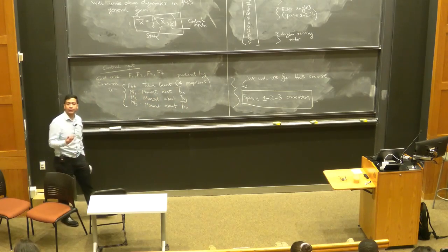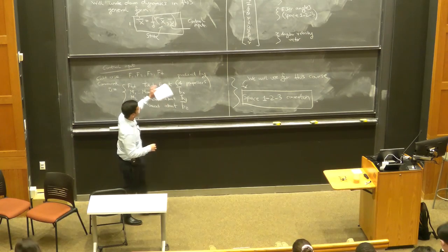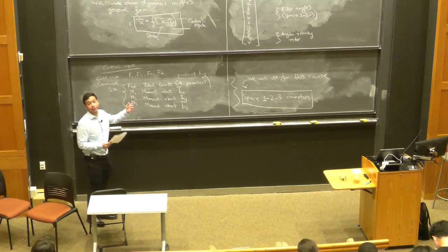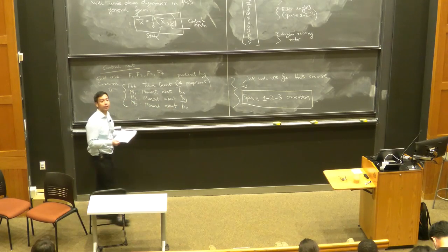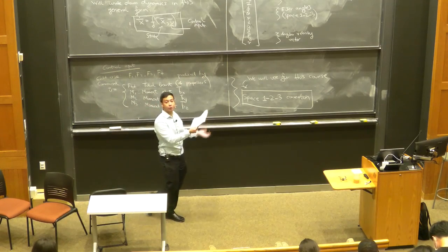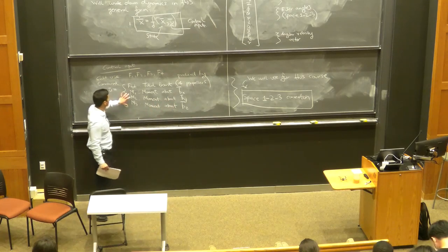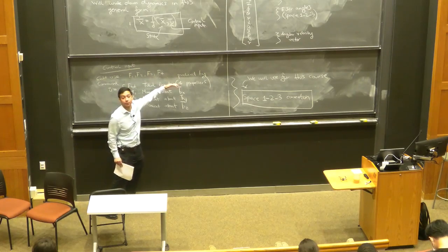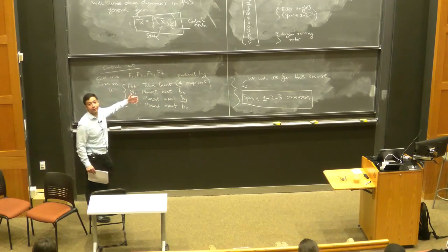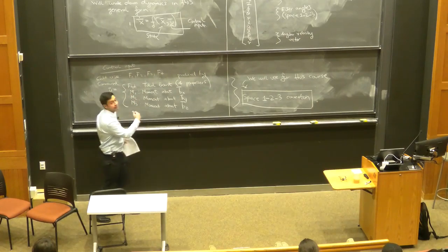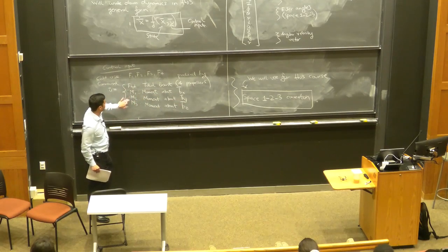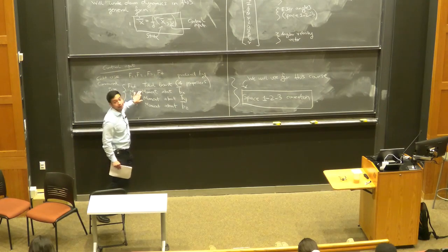This is similar to what we did with the planar quadrotor, right? If you look back at the equations of motion we wrote down for the planar quadrotor, we wrote them in terms of two control inputs, U1 and U2. U1 we defined to be the total thrust, U2 the total moment. So this is analogous. U1, the first component, F total of the control input vector, is the total thrust produced by the four propellers. Because we're working in 3D, the net moment, the net torque, is not just about one axis, but about three different axes, Bx, By, Bz. So the control inputs M1, M2, M3 correspond to the net moments produced by the propellers about these three axes.